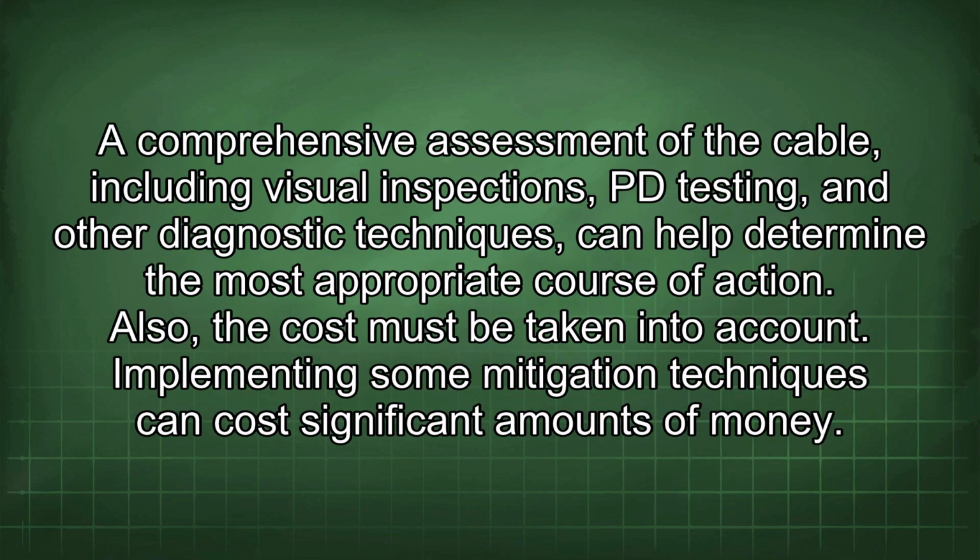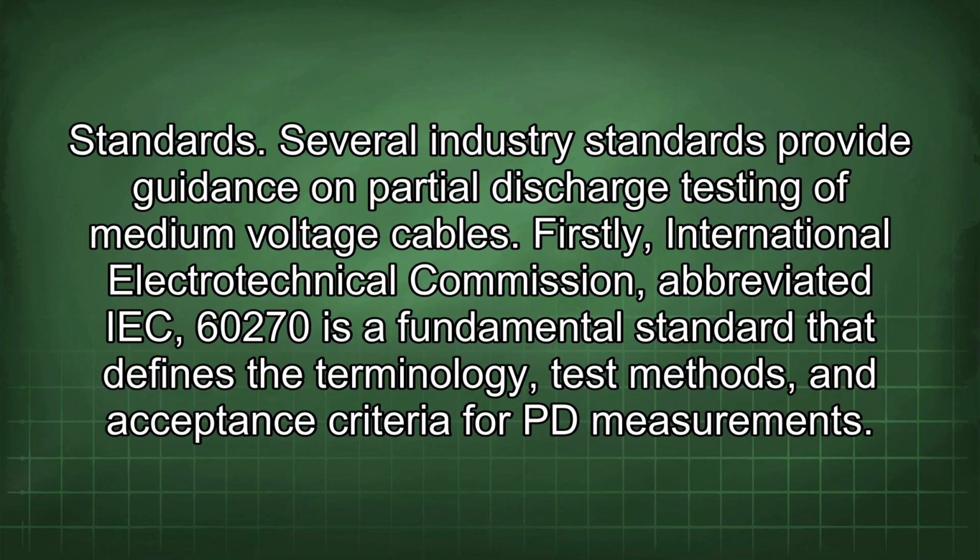A comprehensive assessment of the cable, including visual inspections, PD testing, and other diagnostic techniques, can help determine the most appropriate course of action. Also, the cost must be taken into account. Implementing some mitigation techniques can cost significant amounts of money. Standards. Several industry standards provide guidance on partial discharge testing of medium voltage cables.